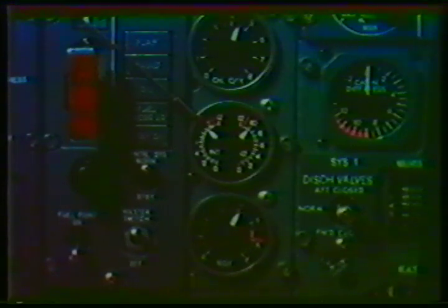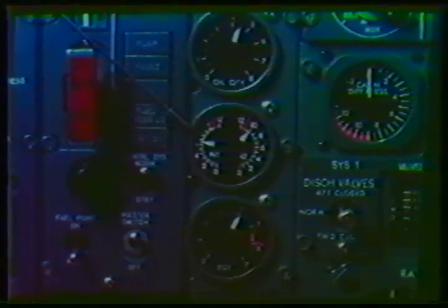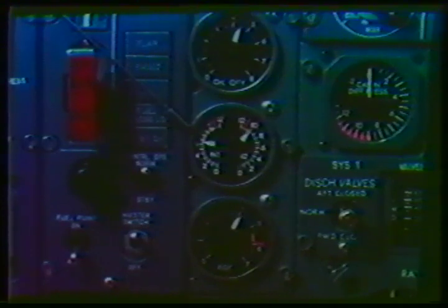If the APU air supply is used to start an engine, when the start push button is depressed, it causes the APU N1 to increase to 91% in order to provide sufficient air from the APU for engine starting. At the end of the starting sequence, when N2 reaches 45%, the start push button pops out and the APU RPM returns to its previous state. In the event of a restart in flight, the lighting sequence of the start push buttons is modified according to the pack valve position, as will be explained in the air conditioning course.